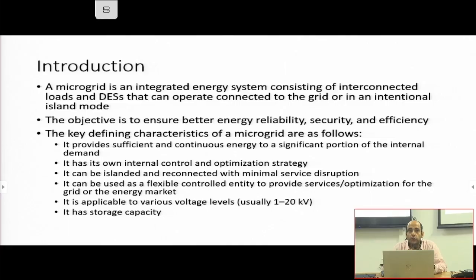You have to understand the microgrid like a conventional grid, only the difference is the size. So it should have its own proper control and regulation. You should not think that because it is a very small system, it can operate randomly. Even if it's a microgrid of small size, the frequency, voltage, active power, reactive power, whatever your variables are, have to be properly controlled and coordinated.